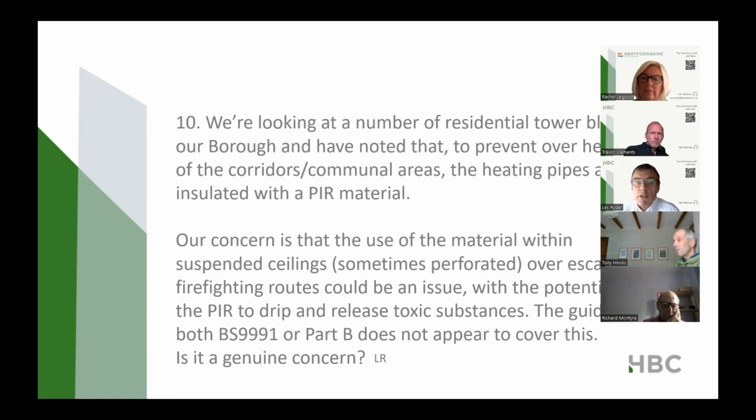It's not only for keeping the corridors cool, but also in many of the larger flats with communal heating, there'll be a flow and return in there as well. So the flow and return will be insulated, so it's not only to stop the corridor heating up, but it's also to stop any heat loss through the pipes. But like I'm saying, my feeling is, and again, it all revolves around the other areas.